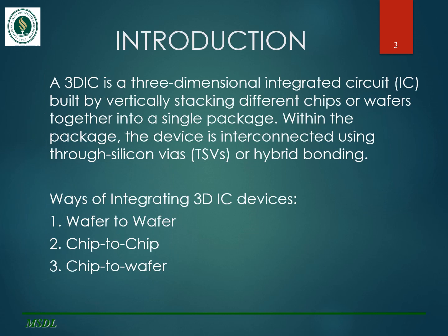Over the last few years, we have seen tremendous technological and economic progress in semiconductors and microelectronics, following what is known as Moore's law. According to Moore's law, every 2 years, the amount of transistors we can integrate on an IC doubles. This exponential increase in integration is achieved by scaling down the dimensions of the microcircuit by a factor of 0.7 at every technological node.